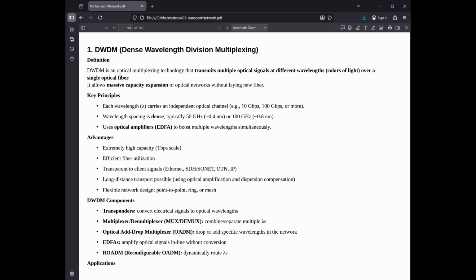To build a functional DWDM system, several specialized components must work in harmony to convert, combine, transport, and amplify light signals. While the fiber optic cable is the physical path, the following components provide the intelligence and muscle. 1. Optical transponder, wavelength converter. The transponder is the entry and exit point for data. It acts as an OEO, optical converter.